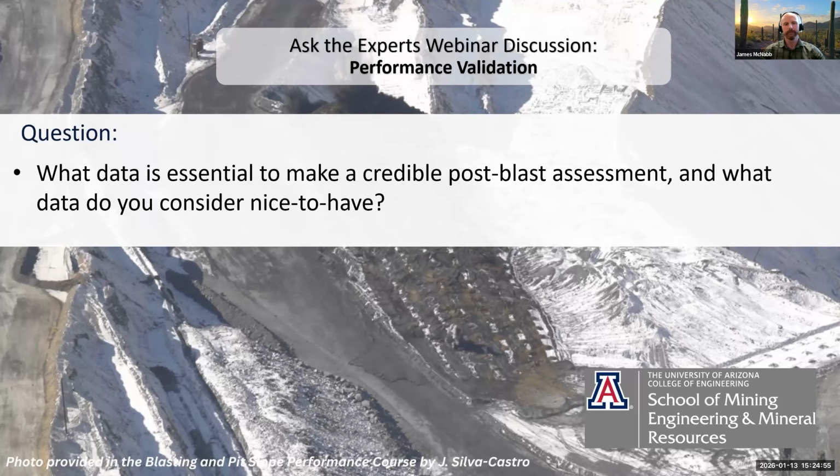Nice to have, and things that need to be done occasionally, is some seismograph data to let you confirm that your near field PPV values at the slope are close to those that are predicted. Frequently you go to mine sites and there's a lot of design work done, but very little verification. That's a nice to have, but I think we could do it more often. Thank you. I think that's probably my response.